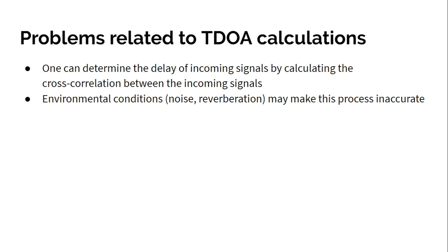So what is the principle behind the cross correlation here? If we have a setup with only two sensors, which is really common actually, we calculate the cross correlation between the incoming signals in each sensor, and then we check where the global peak of the function happens in the time domain, and that's going to correspond to the time difference of arrival.